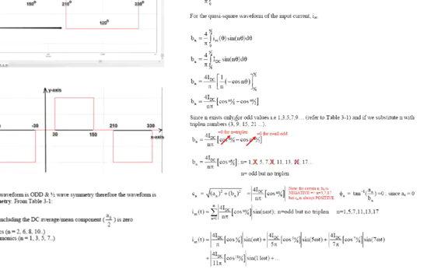So since n exists only for odd values, 1, 3, 5, 7, 9, because of the odd and quarter wave condition, if we substitute n with triplet numbers, 3, 9, 15, 21, and so on, we're going to see that the first component here, which is cos n pi over 6, will go to 0 for n triplet. And the second component here, which is cos n pi over 2, will be 0 for all n odd harmonics. These terms always go to 0, but the first term here is only 0 for triplet harmonics 3, 9, 15, 21.